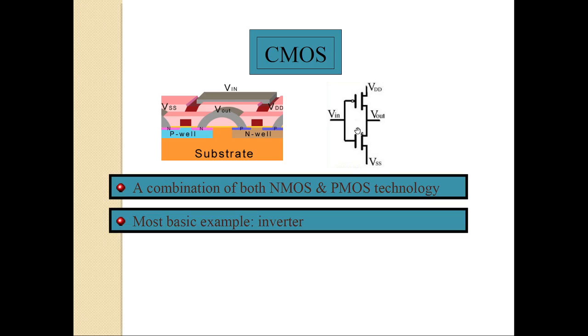So how to remember? For PMOS, if we are applying 0, then it will conduct, and whatever is at the drain, it will pass. In NMOS, if you are applying 1, then it will pass whatever I have connected at the source to the drain or drain to the source. Like this only it will come. So this is nothing but my complementary MOS.